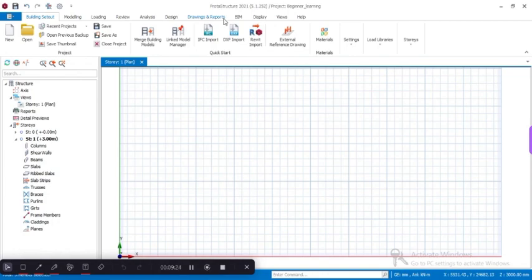Now on importing floor plans. Floor plans can be imported and transformed into 3D elements, a model element. Like I did there, I explained how you can import both the beams, the columns and everything from your AutoCAD drawings, the architectural drawing, straight to Prota. And also you can import the grid and everything. So it explains how the layers and everything have to be set on AutoCAD before you can import it into ProtaStructure.